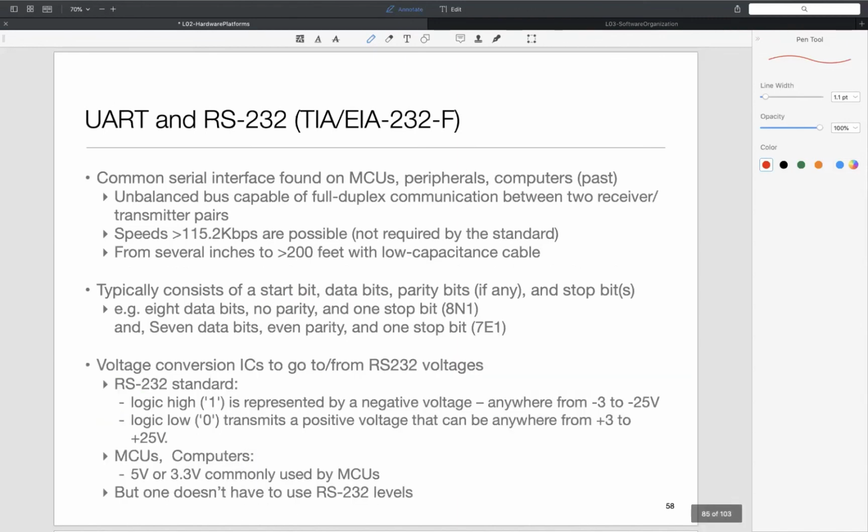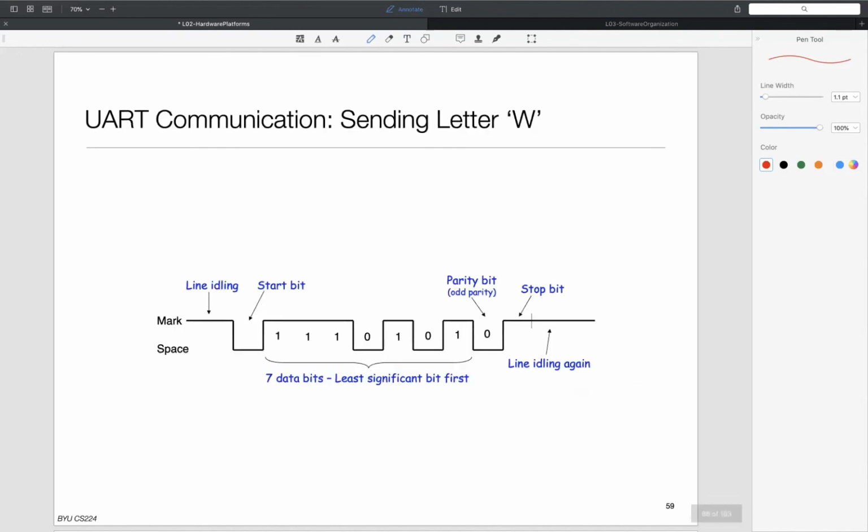Okay, I don't think I need to spend much time on this. The main thing internally is that there's no separate clock going out. As I'm sure you must have seen in some undergrad course or other, the way the receiver works is that by looking at the start bit, you measure what the precise clock rate is. The challenge we face is that clocks on the two sides may not have exactly the same frequency.